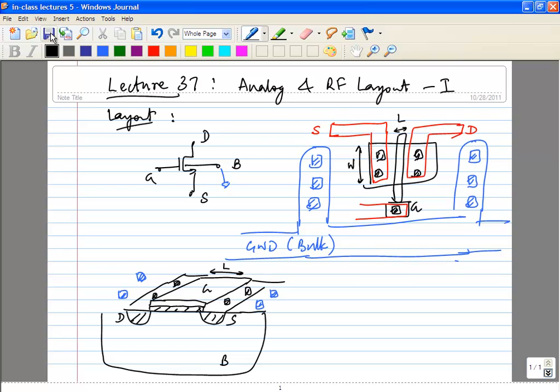Typically the way it works is, before the layout engineer starts working on it, the designer needs to design the circuit such that it can be laid out directly, preferably giving some information on the signal flow, because the layout engineer will typically not know a lot about the design of the circuit itself. He won't know which lines are critical. So what you will have to do as a designer is do what is called a floor plan.